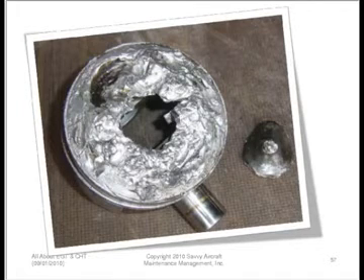Here's what happened. It holed the piston. It melted the hole in the piston, and you can see that the piston crown was clearly above its melting point, and there's all sorts of molten metal all over the place. You can imagine the state of the rest of the engine after this thing came apart. Not a pretty sight.